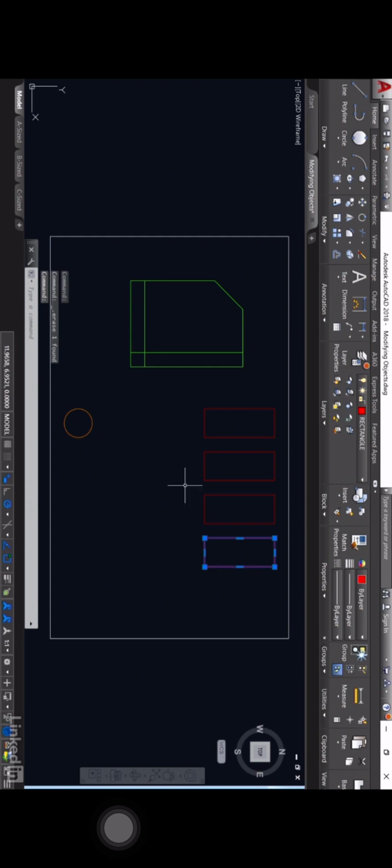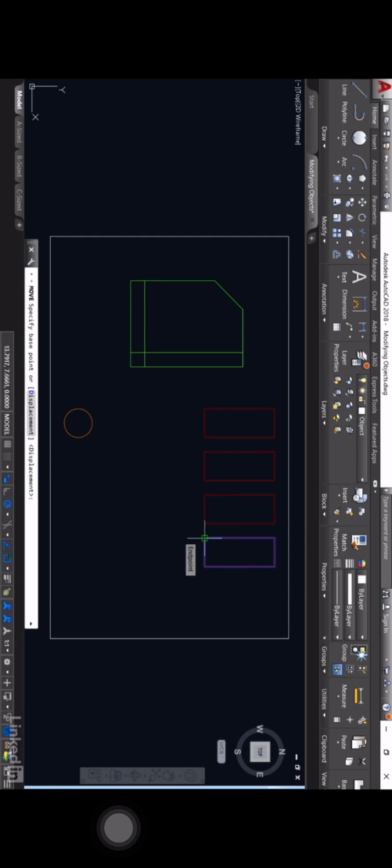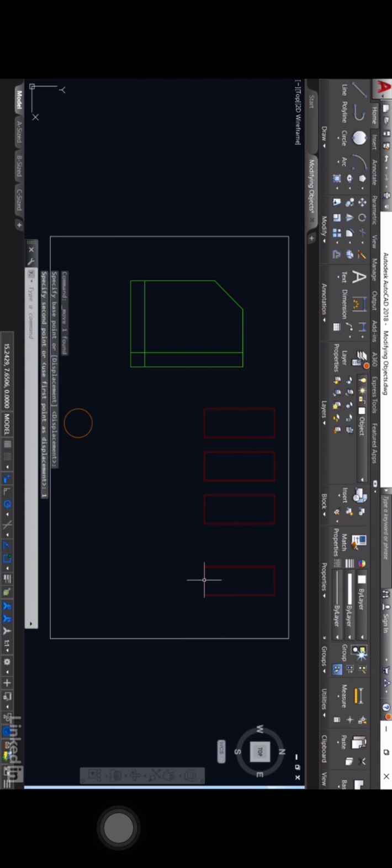We're going to move this rectangle here. So I'm going to click on it, right-click, and go move on the shortcut menu, bottom left corner as the endpoint snap, click on it, drag it to the right using the polar tracking, and type in 1 as the distance to move, and then enter to finish. Just gives us a bit of space. Now we're going to rotate that particular rectangle. Again, rotate is on the modify panel on the ribbon on the home tab.